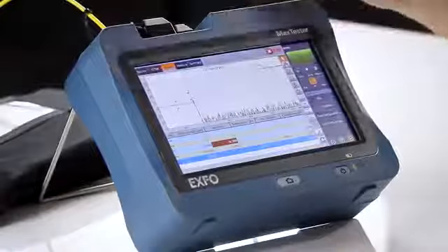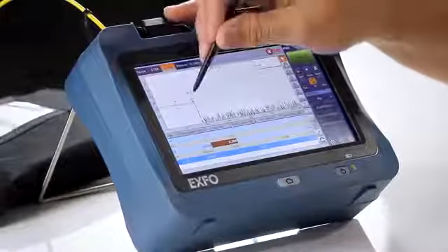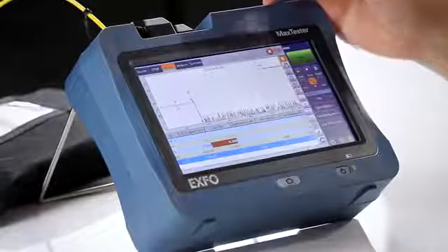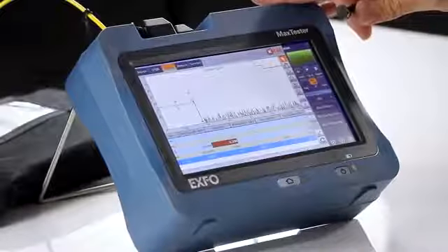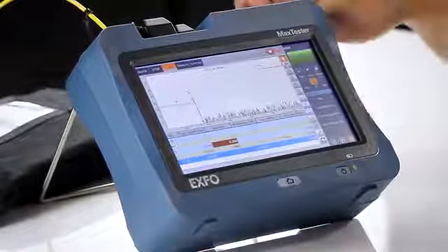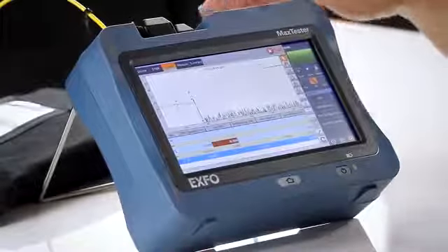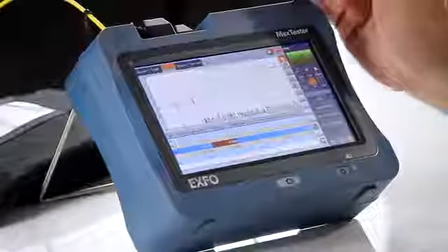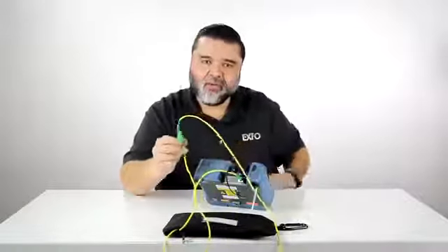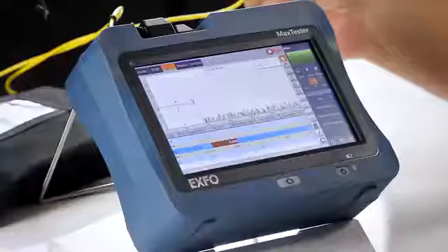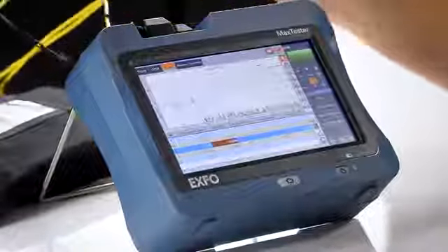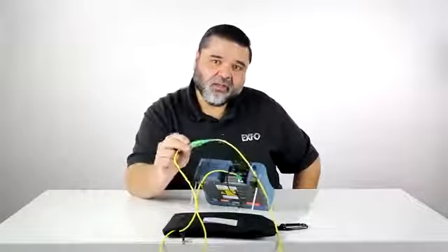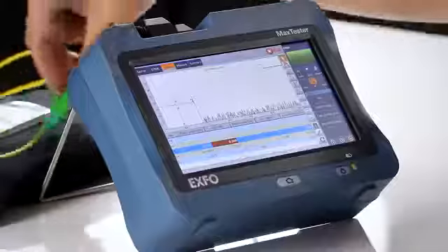So I'll go ahead and select the event table and then look at it. And so I will select the end event. And so right now we are testing 161 meters. And so the reason why I have about 300 meters of fiber up here, but 150 meters, remember during the setting, I nulled out. So there in the middle, we have this connector. So I have a connector here right in the middle of the fiber. And this one has 0.3 dB of loss and no detectable reflection. But this is an APC connector, so we expect it to have good reflection if it's clean and connected properly.